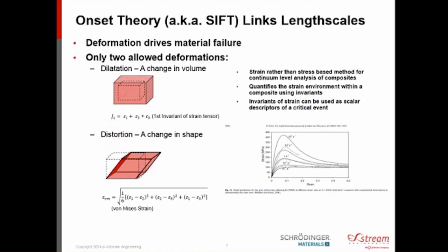So what kind of failure theory links these things together? If you look at traditional failure theories in structural analysis, you'll find that nearly all of them, or all of the traditional and heavily used ones, are ply level analysis and assumptions where they look at the plies as homogeneous materials and then define a failure envelope around them using ply level failure testing.